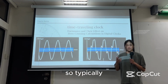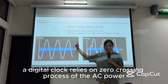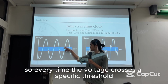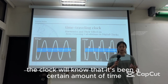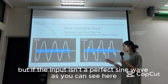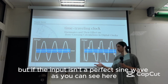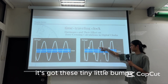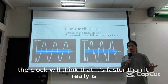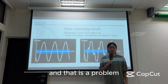So typically, a digital clock relies on zero crossings of the AC power grid to calculate time. Every time the voltage crosses a specific threshold, the clock will know that a certain amount of time has passed. But if the input isn't a perfect sine wave, as you can see here, it's got these tiny little bumps, the clock will think that it's faster than it really is because the voltage crosses the threshold multiple times. And that is a problem.